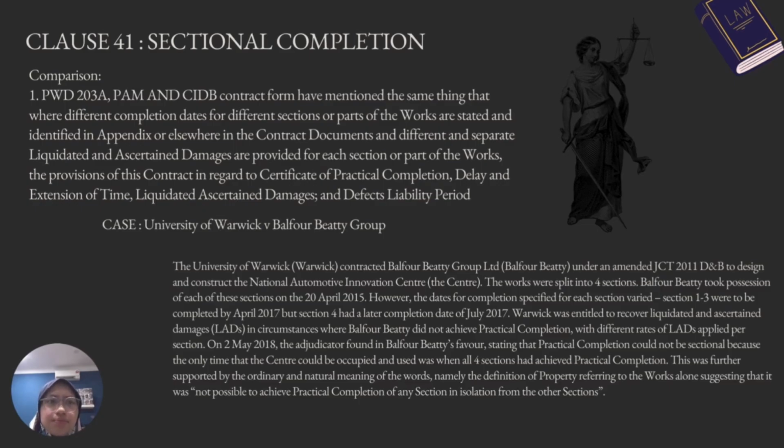Next, clause 41, sectional completion. Comparison. PWD 203A, PAM and CIDB contract forms have mentioned the same thing, that where different completion dates for different sections or parts of the work are stated and identified in the appendix or elsewhere in the contract document, and different and separate liquidated and ascertained damages are provided for each section or part of the work, the provisions of this contract in regard to certificate of practical completion, delay and extension of time, liquidated and ascertained damages, and defects liability period apply.